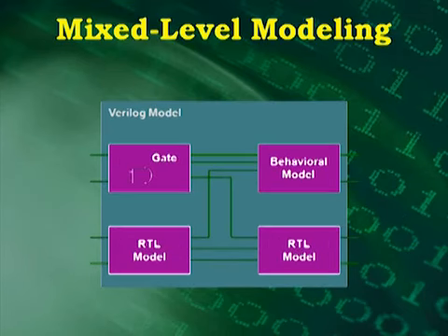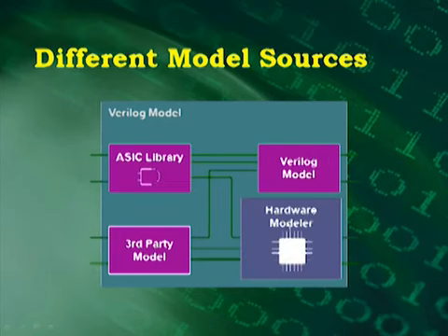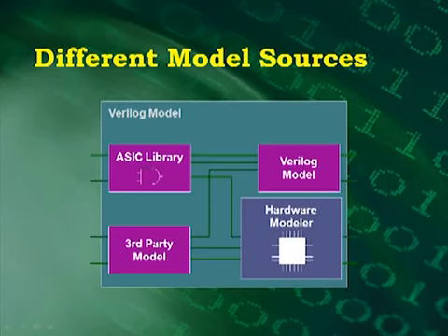You can also mix these models. Okay, you can use behavioral models, RTL models, gate level models, all within Verilog. Okay, maybe even something from a third party, like I said, IP, or a hardware modeler. You can join all these together and use them all.